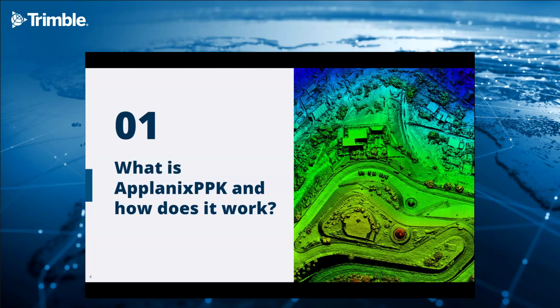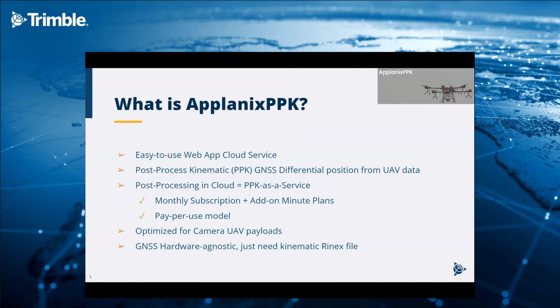Okay, so what is ApplanixPPK and how does it work? ApplanixPPK is a very easy to use web application that uses a cloud service infrastructure at the back end, and it allows you to post-process kinematic GNSS differential position data from UAV data and/or drone data. So this post-processing is really happening in the cloud backend.